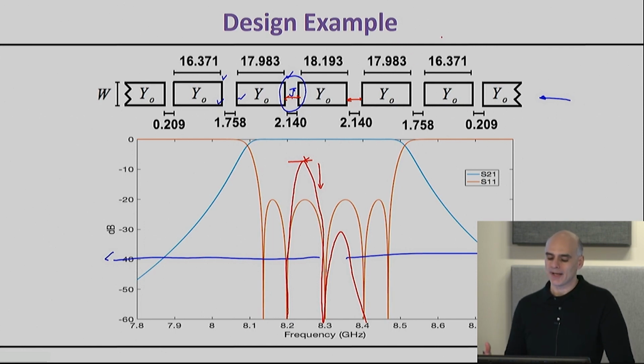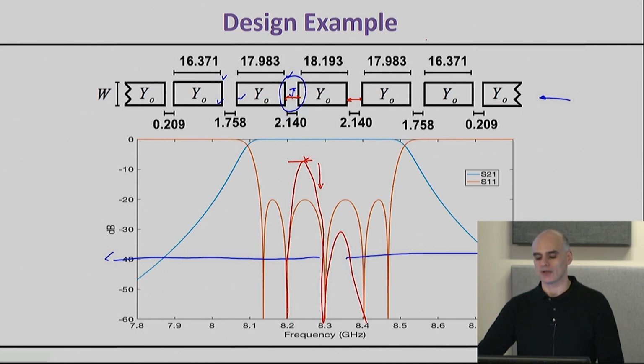Now, of course, then finally you'll have to make the circuit. You'll have to fabricate things. As I mentioned, there will be likely fabrication errors. So as the very last step, there might be some trimming that you need to do right on the layout. So it depends really how accurately you want to hit the response of your filter. But if you want to really hit the specs without any unknowns, it may take a couple of iterations to make your filter and basically trim it.